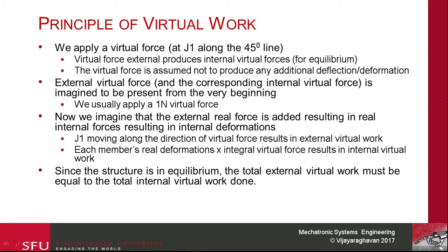Now, since our internal virtual forces are present from the beginning of time, when each of the links deforms due to real deformation, the product of the real deformation and the internal virtual force results in internal virtual work. Since the structure is in equilibrium, we're going to equate these two terms.